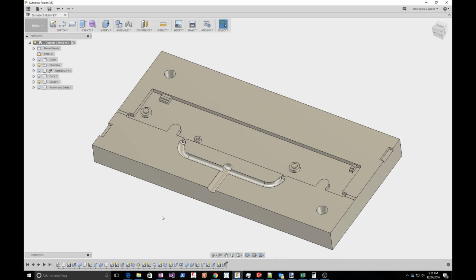When this is a production mold, I probably want to have them captured in there. I'm also going to want to have it be a press fit on one side and a loose fit on the other side. So I'm going to mill these holes slightly undersize, and then I'll use a reamer to increase the size. I'll use an undersize reamer on one side, which will be the fixed side, and then I'll use an oversized reamer on the other side, which will give me a loose fit, and that'll be the sliding side.